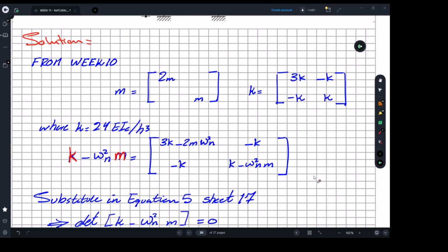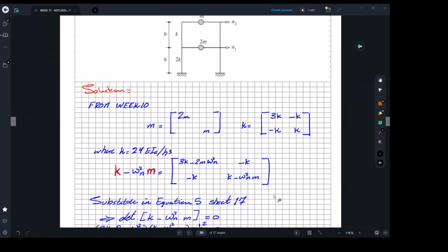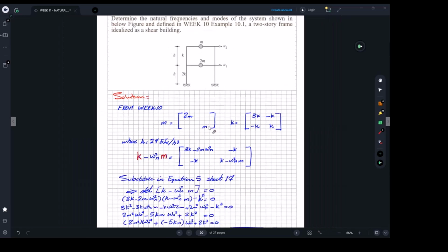But remember, they are not for the entire building. The software will repeat all those calculations and look at element by element. It will start looking at the ground floor and check wall by wall and column by column, and consider that each is an element by itself. But usually the building will be more flexible than a piece of column which is only 3 meters high, because your building was much higher. So it's more severe, and it's an easier shape to happen. Usually the software will set the first mode as the one that's easier to happen, and then take it from there.